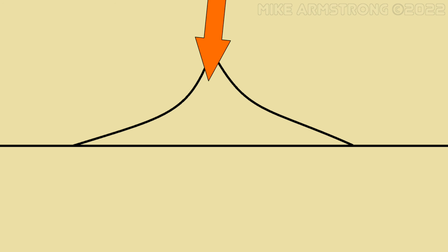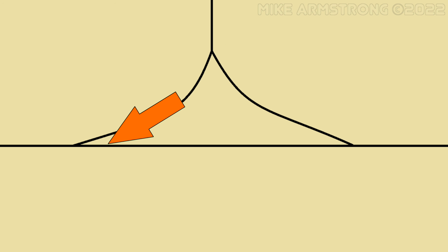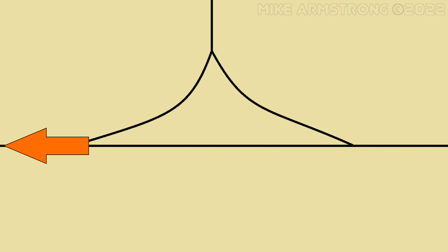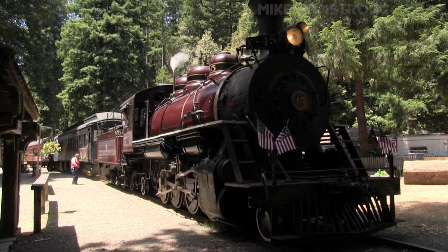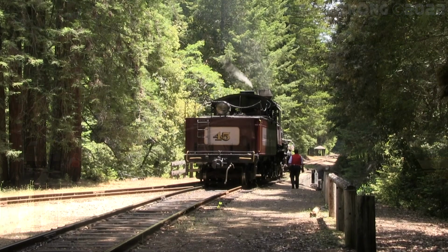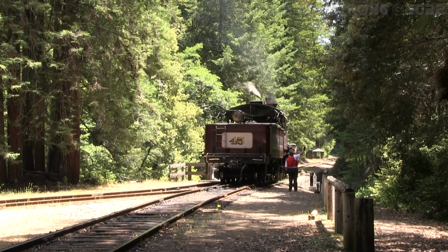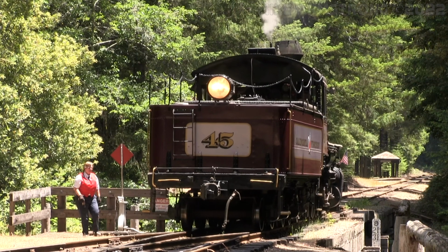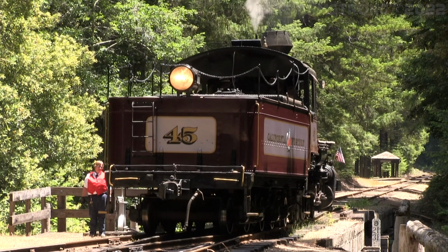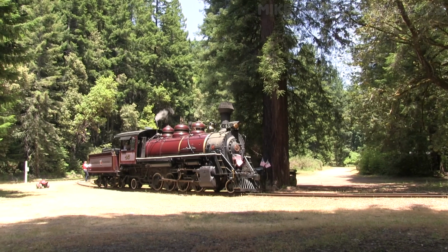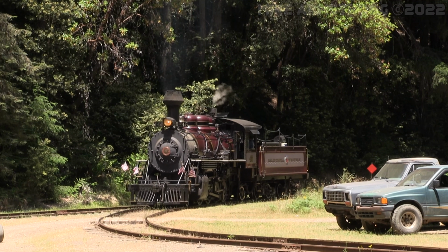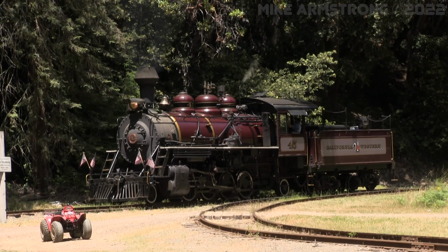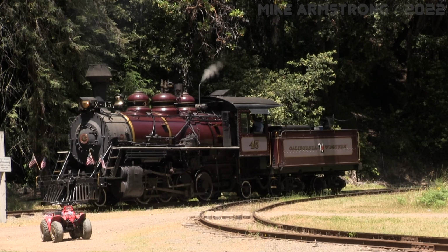In order to turn around using a Y, a train can either travel past both legs of the Y and then back in, or proceed directly into the Y and then back out. Ys are helpful in that they can be used for reversing entire trains at once, although it is relatively unusual to see longer trains being turned in this fashion. They also require fewer changes in direction to complete the reverse move than a runaround track. Of the turning methods, Ys are often the most expensive to construct as they take up a lot of space.